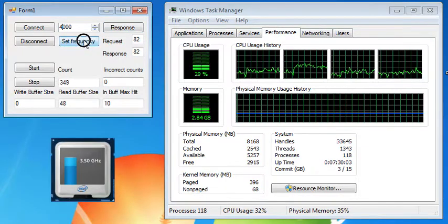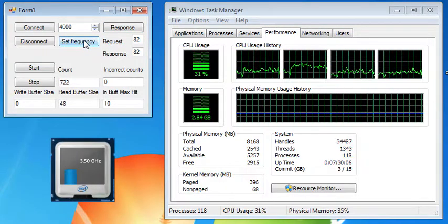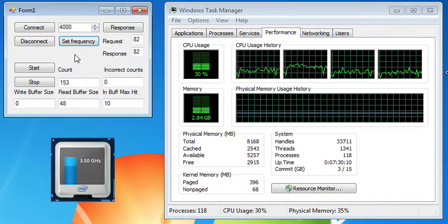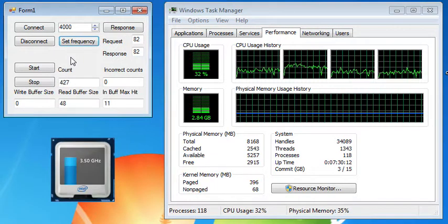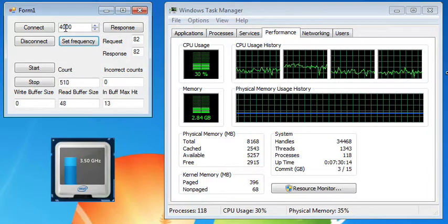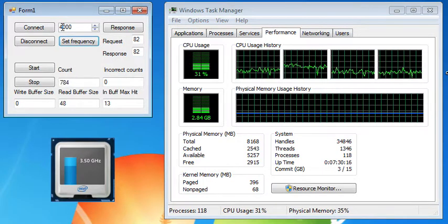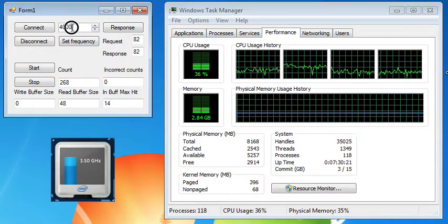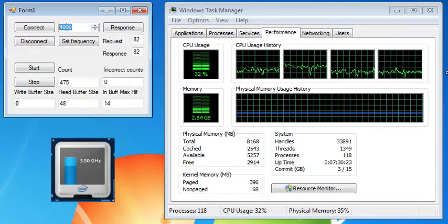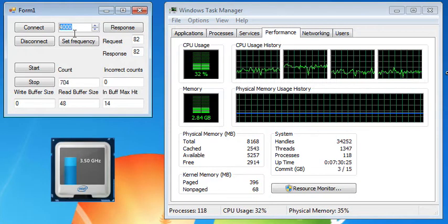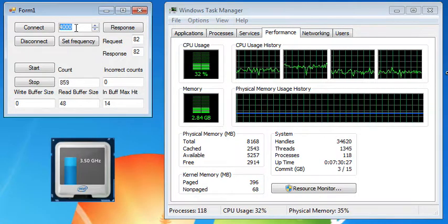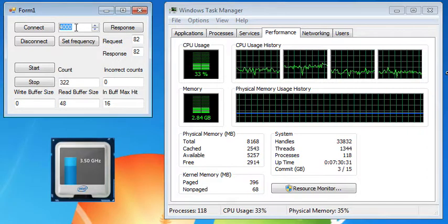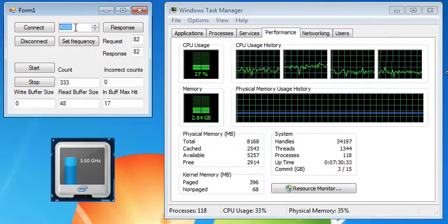4000 Hertz. At this point, the frequency we have set, we don't think the microcontroller can actually exceed this value. We've not actually tested to see if the microcontroller is sending at 4000 Hertz, but we can safely assume that this is far faster than the 100 Hertz maximum which the aero-quad software will update our computer at.